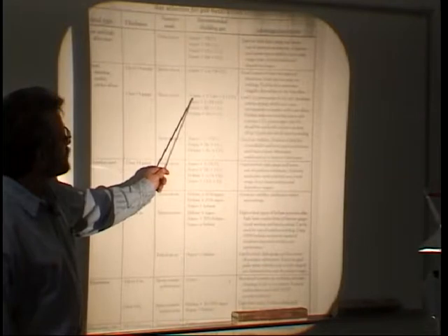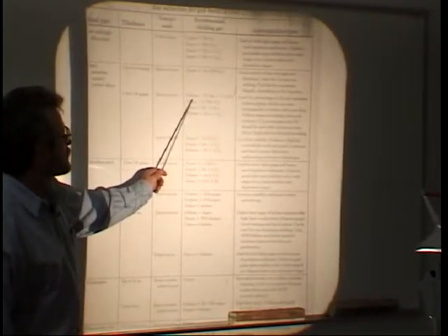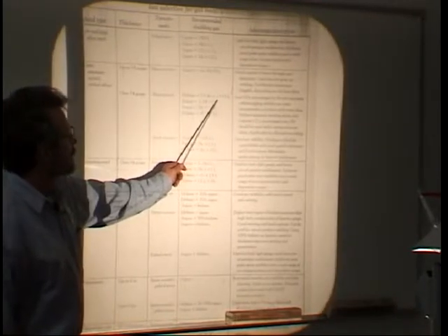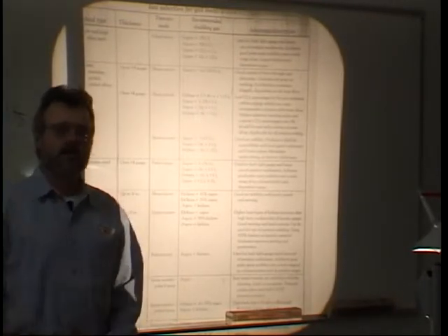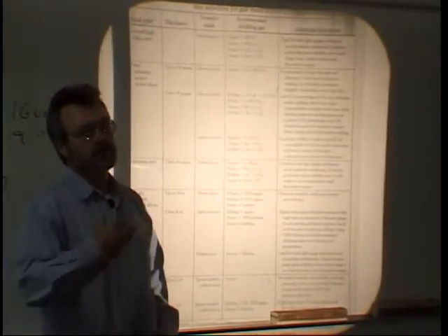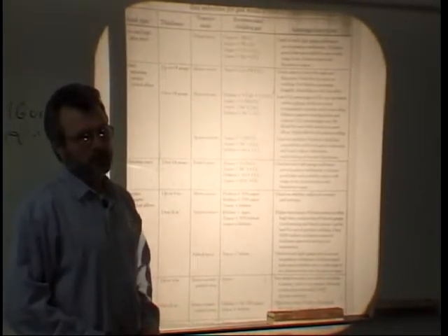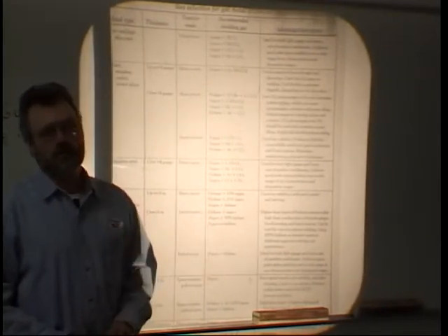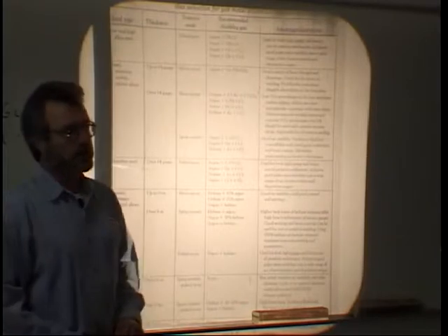So now we've switched mostly to helium. 90% helium, 7.5% argon, 2.5% CO2. Because helium is a better heat transfer gas than argon or CO2. Generates higher temperature at the weld puddle, and therefore we're able to melt that stainless steel, get better depth of fusion, and we can weld with it properly.